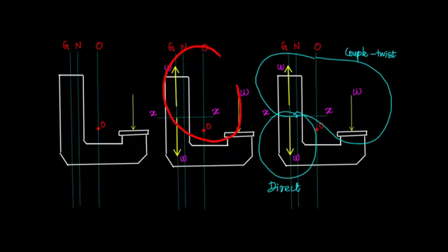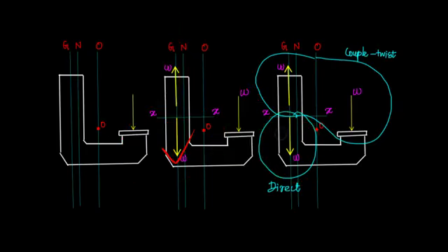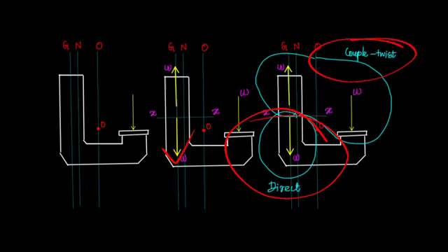Okay, fine. Now among the three forces, one force is there and I have added two forces. Among the three forces, two forces will form a couple. Now see where the remaining one force is. The remaining one force is acting along the centroidal axis in the downward direction. Downward direction is kind of a pulling force. So there will be a direct tensile stress. So among the three forces, two forces form a couple and the one remaining force is kind of a tensile force. So we have to calculate the direct tensile stress and a bending stress.